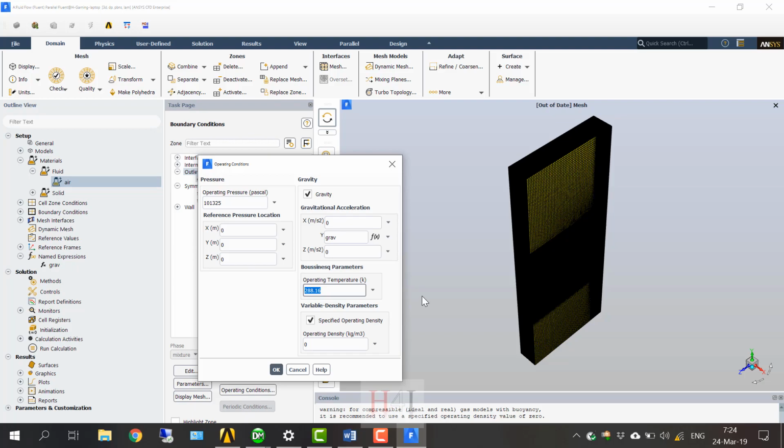Understand this or what? This is the operating temperature. This is the temperature of the ambient. I used a density in the equation of the pressure. Do you remember the equation? This equation. This density should correspond to the temperature of the ambient. So it's supposed to correspond to the temperature of whatever you put here. I put here 288, which is 15 Celsius. The density at 15 Celsius is 1.225. If the ambient temperature is 25, you must specify here 298, which is 25. And in the equation of pressure, use the density of the air at 25.